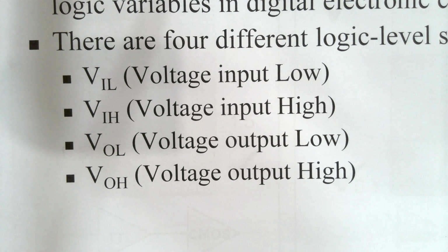So the output, once it has to be logic 0, must take any value within that range VOL. Similarly, for VOH, which is voltage output high, if the output pin has to specify a logic 1, then the voltage on that output pin must take any value within the range VOH.